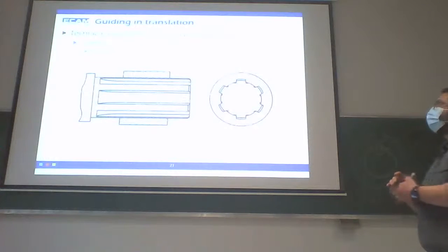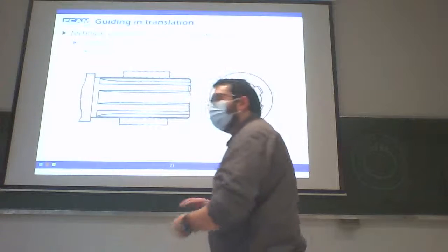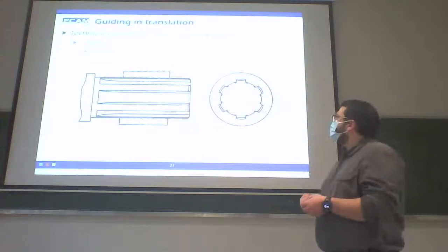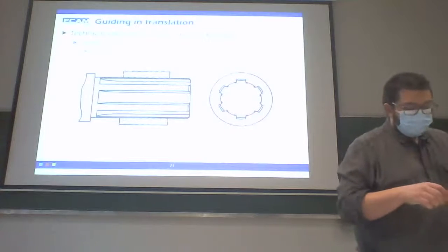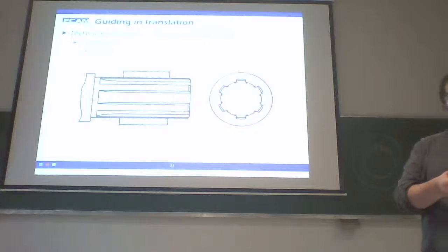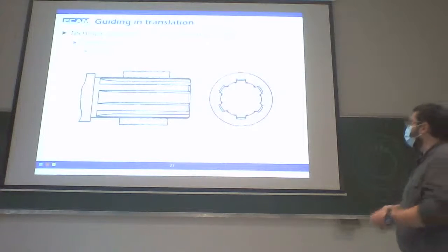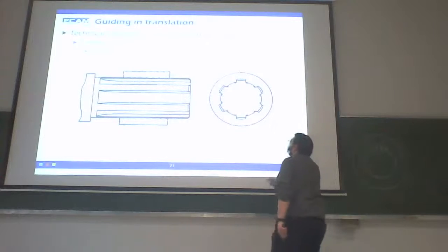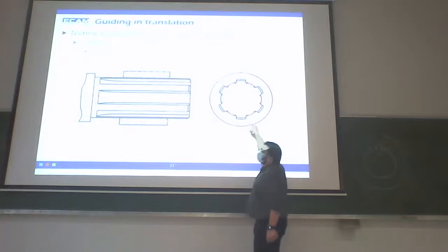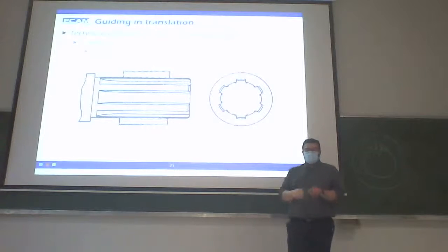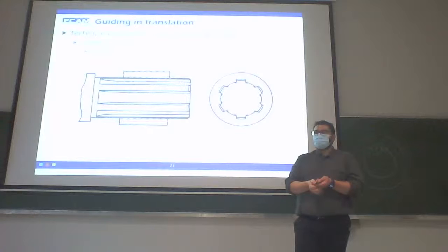Next solution, fluted shaft, is almost like a key, but here, because of important effort, I directly machine the shaft to have this particular shape, like this. It's like we have 6 keys, but they are directly machined, manufactured inside of the shaft.